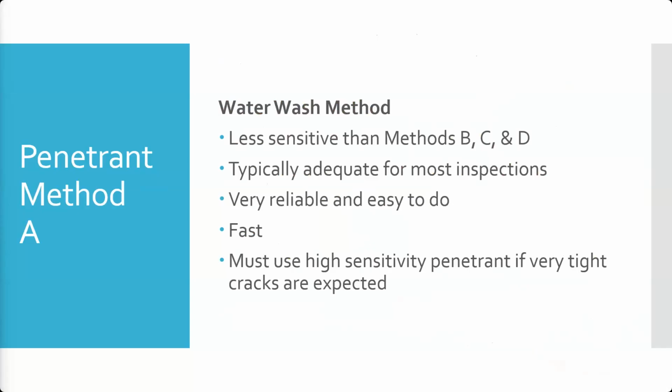And the advantage of that is it's very reliable, easy to do. It's pretty forgiving in terms of the process and what kind of skill the inspector has to have in order to use it. It's pretty fast, minus the one big disadvantage time-wise with liquid penetrant, those dwell times I was talking about, where we have to let that capillary action pull the penetrant into the various cracks and crevices.